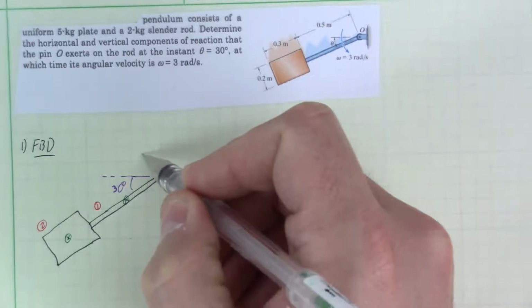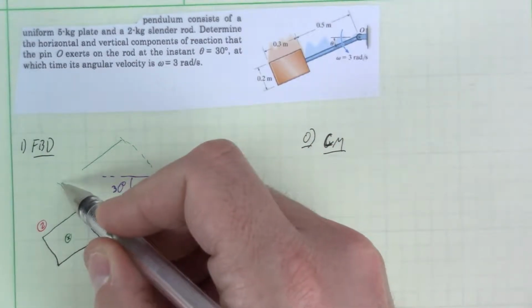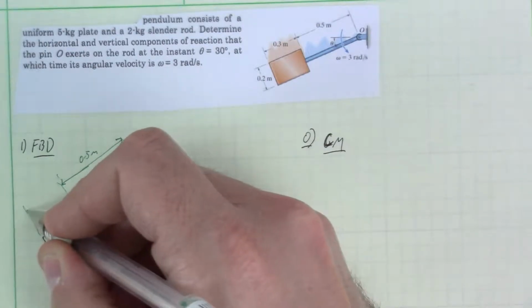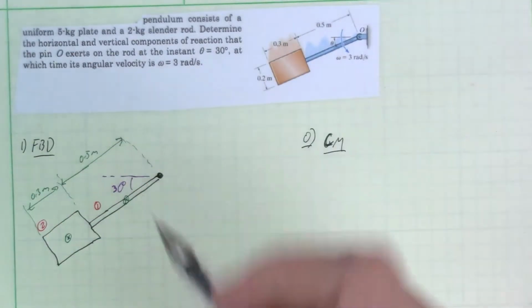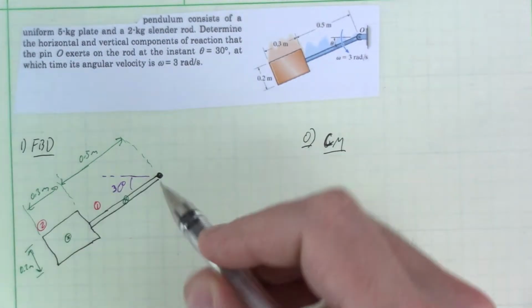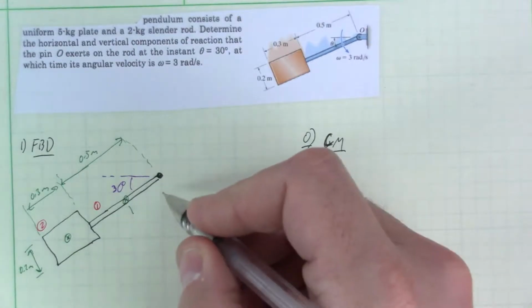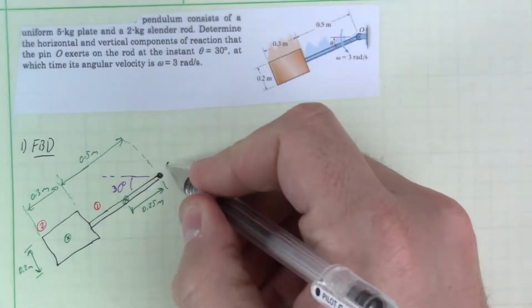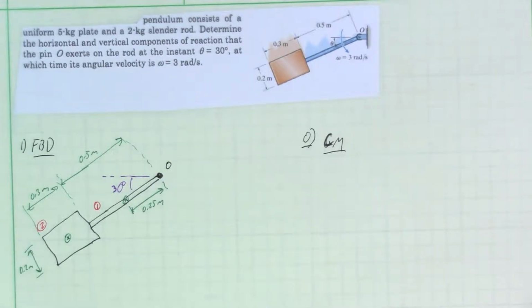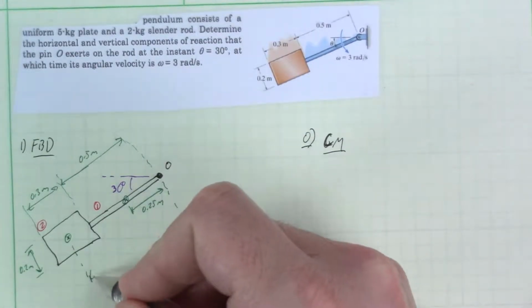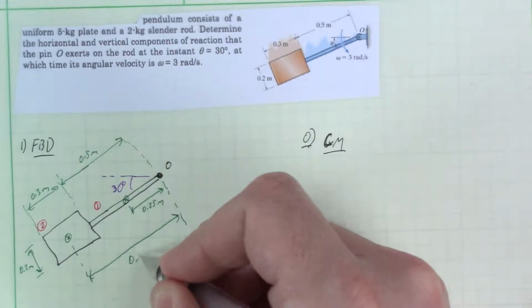And so if the whole thing is, well, let's do it here, right? This to there is half a meter, and then here to there is 0.3 meter, right? Yep. And well, then we also have 0.2 meter. I'm just reproducing what's in the picture. This then is going to be 1/4 of a meter, 0.25 meter, and this is from point O. We haven't even on this free body diagram put any forces yet. It's because we need to know where to put them, right? And think about the mass. That's the only thing acting on this, the reactions and the mass. I need to know where to put the masses. That's what is governing all of this work here before I actually put the forces on there.